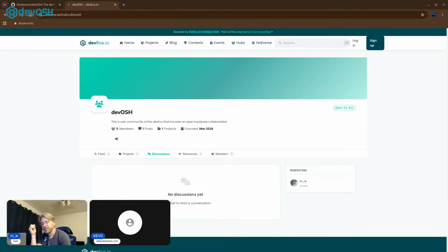The hardware behind the motor. So say you came up with a new driver scheme for your motor. Say you wanted to update the micro stepping on a stepper motor controller that's in the FPGA. You could actually change the hardware algorithm inside of the FPGA to do a little more granular control.